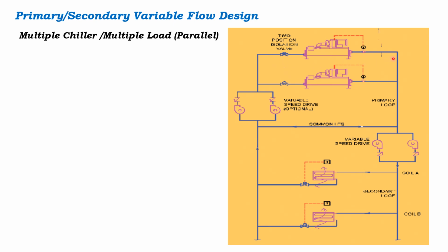In the secondary case, it may be possible that the flow on the primary side is 100 GPM, and if the system is not properly balanced and designed, a case arises wherein 110 GPM flow is required. So the return water, the hot water coming from the system, is going to be bypassed from here, which can create issues in the system.